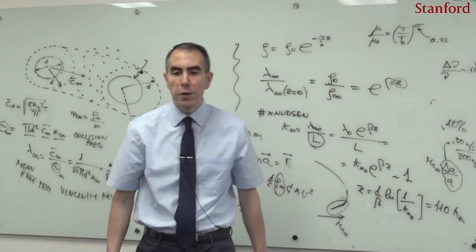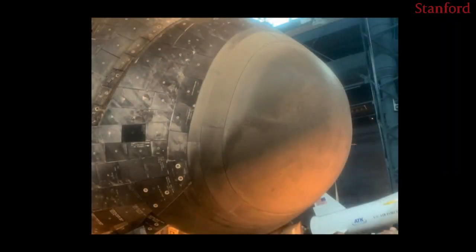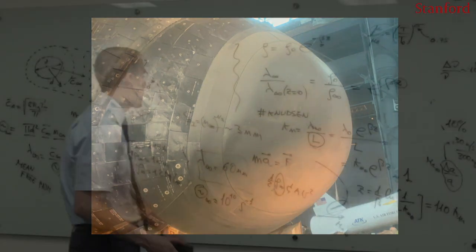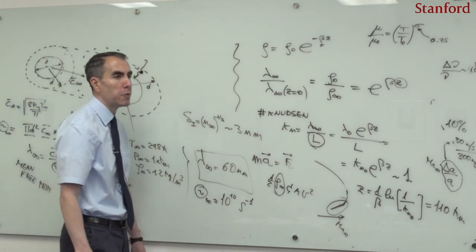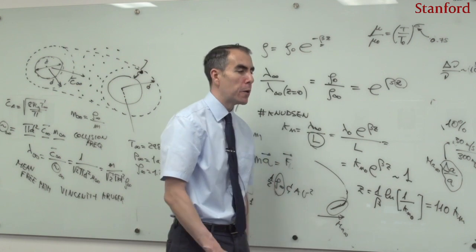So this is to say the following: if we look again at the screen, at 110 kilometers, the mean free path is of the same order as the radius of curvature of this geometry that you have in your screen. So you may be already kind of disappointed, because you will say, well, then the problem becomes almost impossible to treat, because if on top of that one has rarefaction, then what are we doing here?